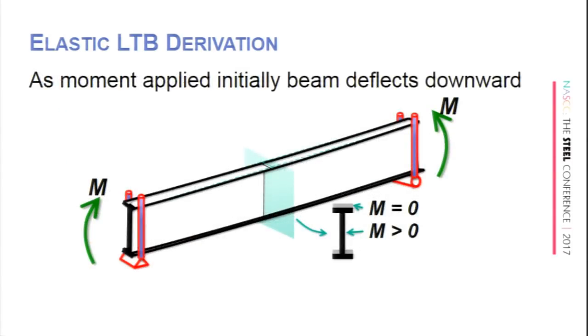So here's that beam, and I finally realized the difference between my experiments because I did not put braces at the ends where you see braces here. But what did I have welded on my specimens? There were vertical stiffeners, flange to flange, on my specimen. So essentially, I didn't need braces because I stiffened that end of my beams to do the same thing as having those braces. Because to set up all those braces and to bring them in is not the easiest thing to do, and to make sure that they're all set properly to your specimens.